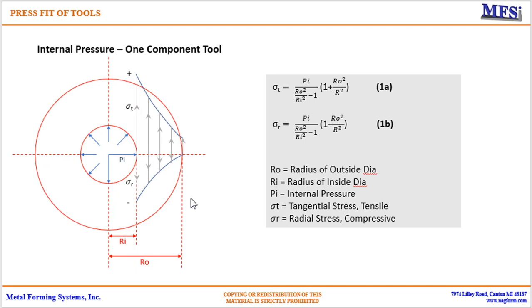And through this compression or interference fit, we can now adjust the stresses in the insert as well as in the casing, so that both of the components have as low a level of stress as possible and none of them yield under the conditions of actual forming of the material. Using this basis, the die press program figures out what is the optimum interference pressure, and also the dimensions that will give us the maximum internal pressure that the assembly can take.